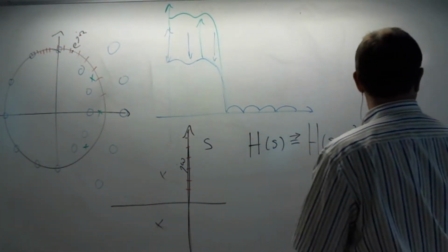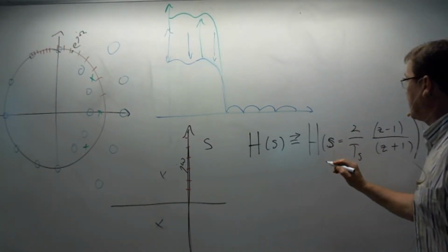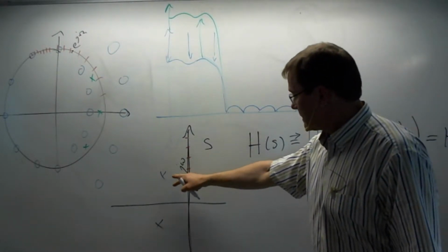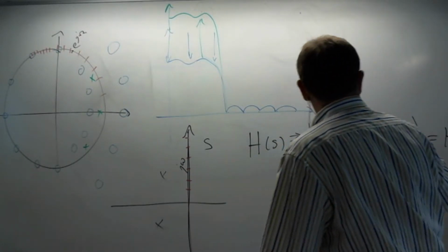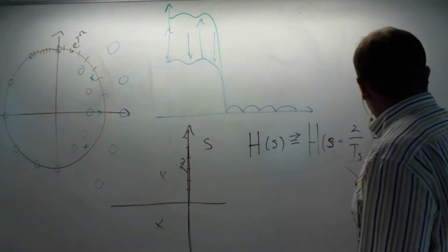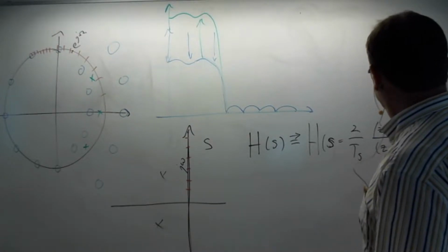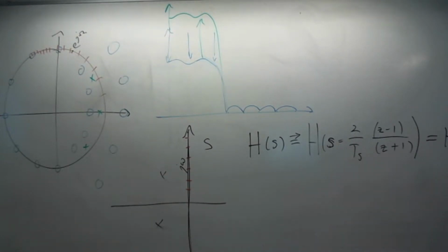And if you have a first order system on the analog domain, then you also get a first order system on the digital domain. It doesn't affect the amount of those zeros and poles. Well, poles yes, but zeros no. No, the other way around. It adds some zeros. So the order number doesn't change, but it warps the frequency scale quite drastically.